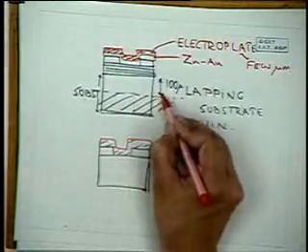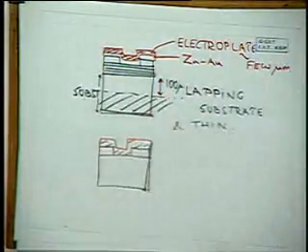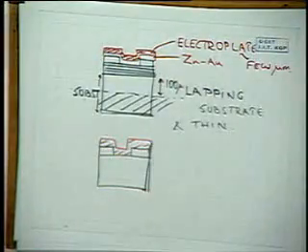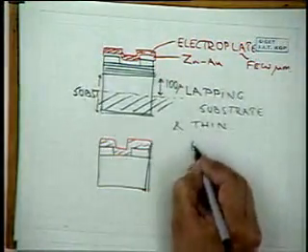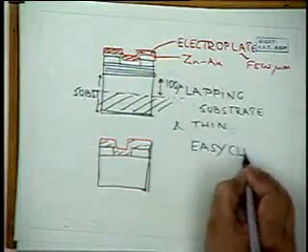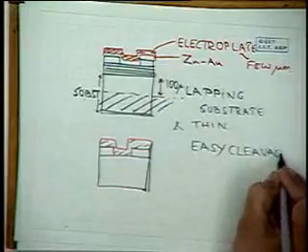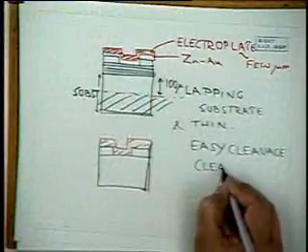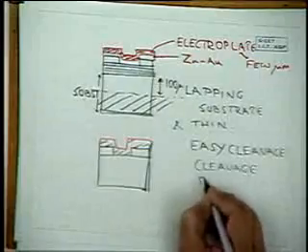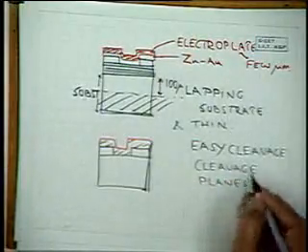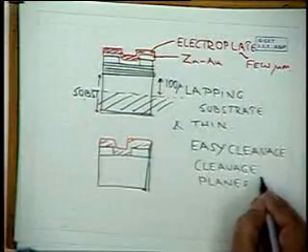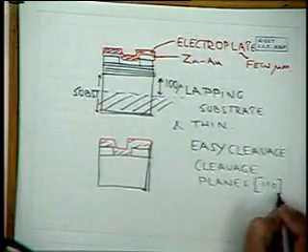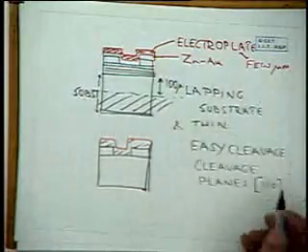Of course, one of the other advantages of thinning, what are the advantages of thinning? Firstly, easy cleavage. What are the cleavage directions in these materials, indium phosphide, gallium arsenide? What are the cleavage planes? Yeah, okay. So indium phosphide also. So cleavage planes are 110. So if you put pressure, it will cleave along 110 because these are non-polar.